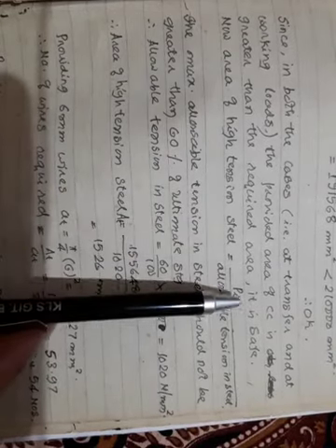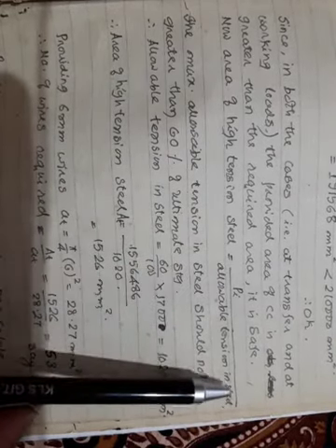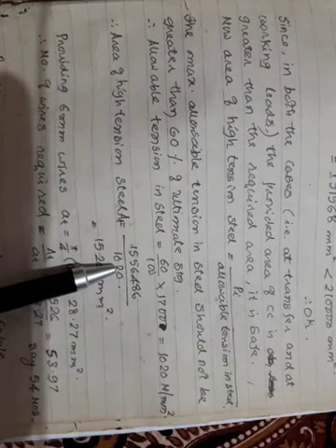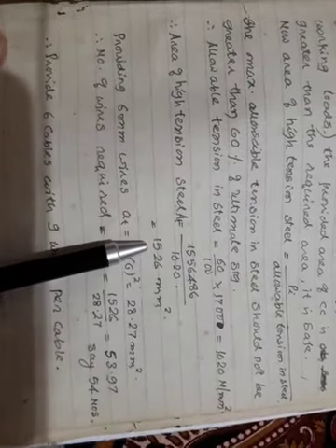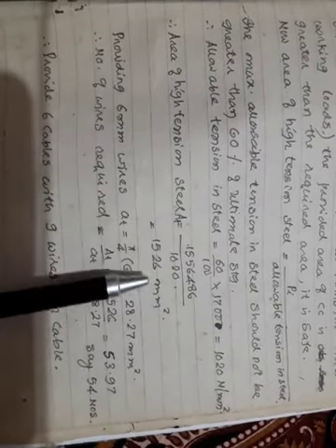Now I think I can easily calculate the area of tension steel. It is Pi divided by the allowable tension. Pi I know, it is so much, and the allowable tensile stress in steel is so much. So it will give me 1526 mm square. In a sense, I need this much area of steel.